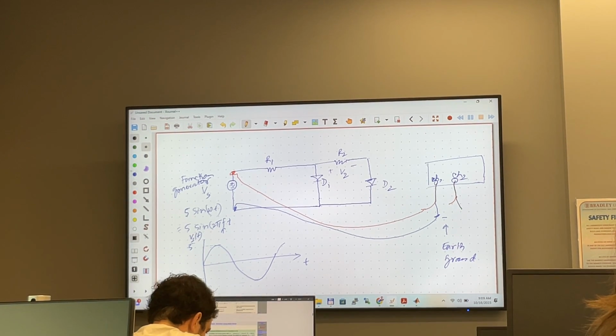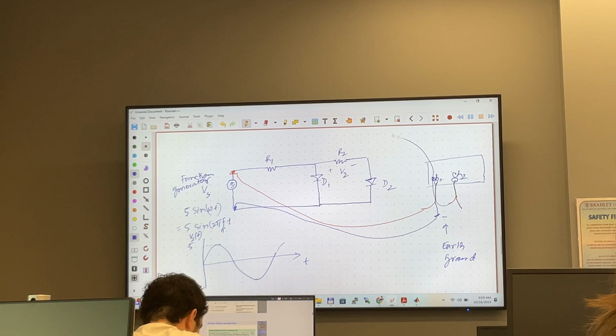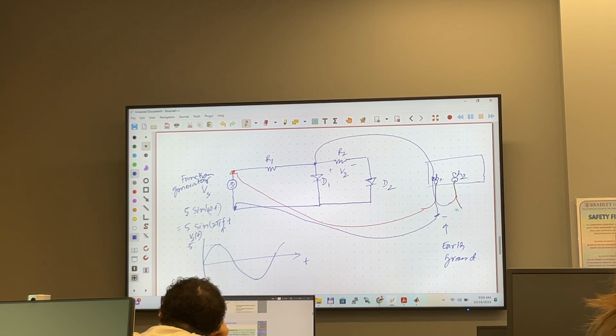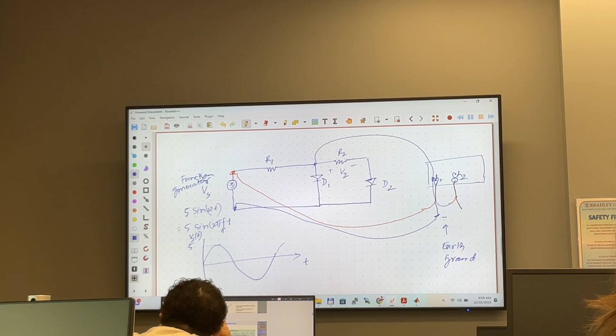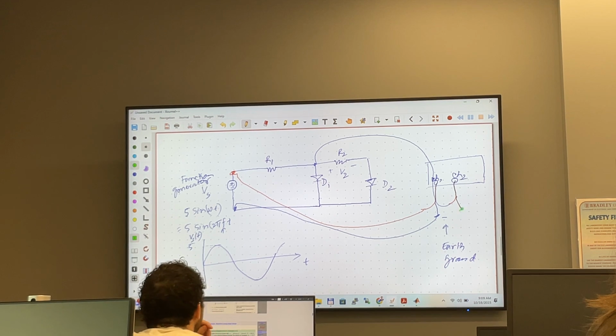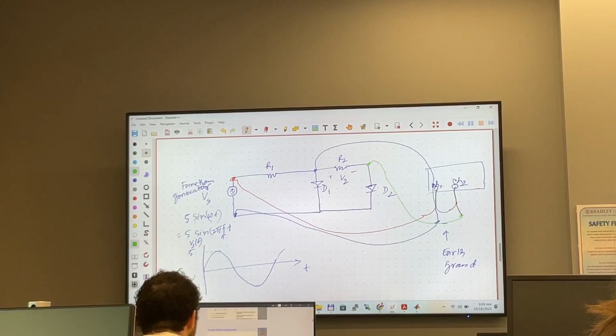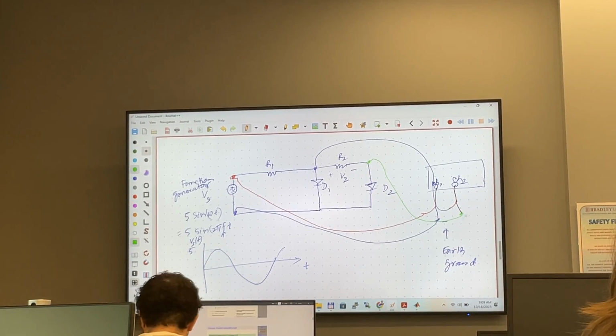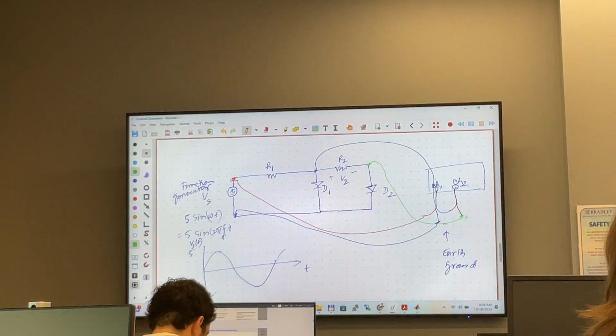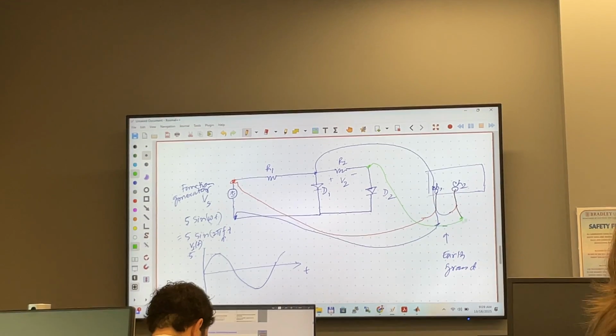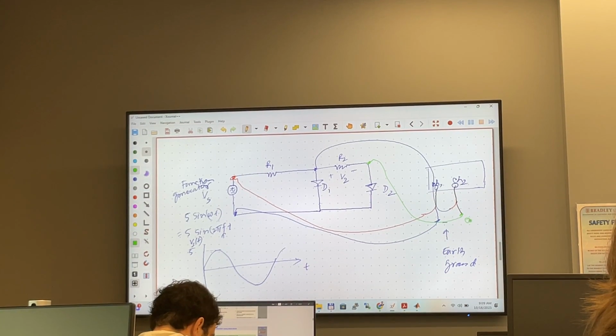What you guys do, you put this one here, and we put this terminal right here. This is incorrect. So this connector here, this is arc ground, which means that this is 0 volt. So you don't connect this negative right here. So in that case, you don't get the actual voltage.